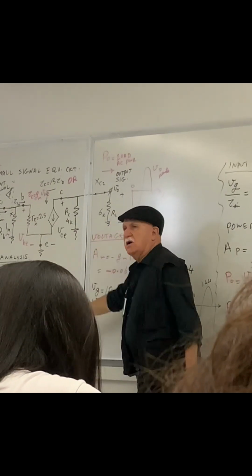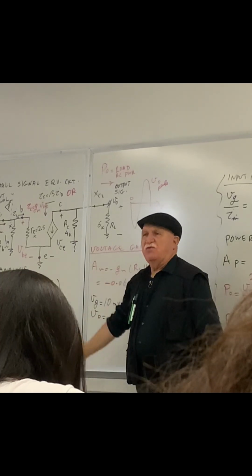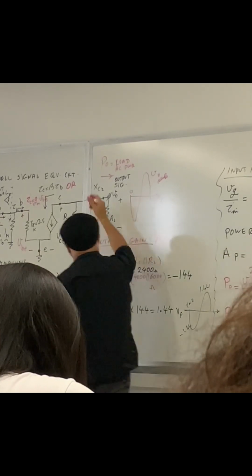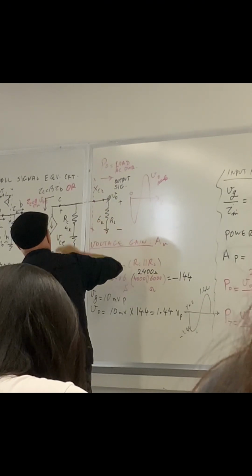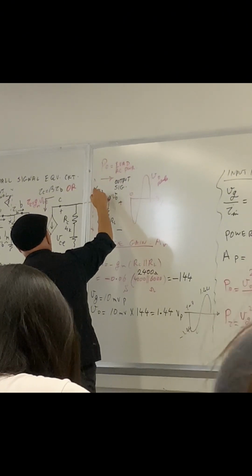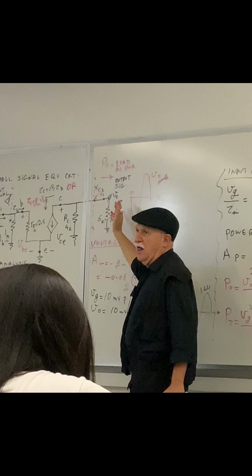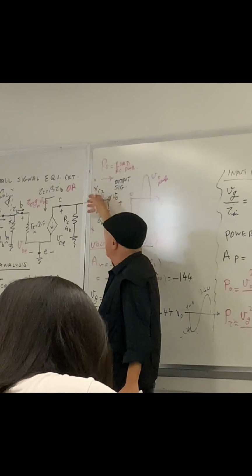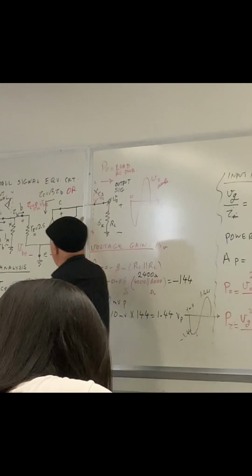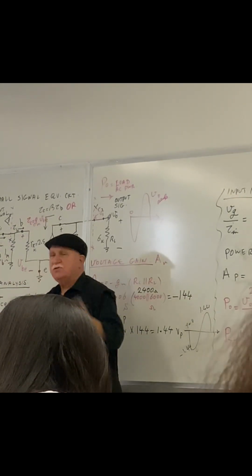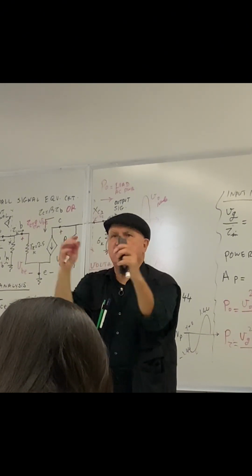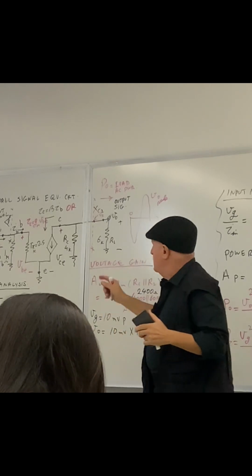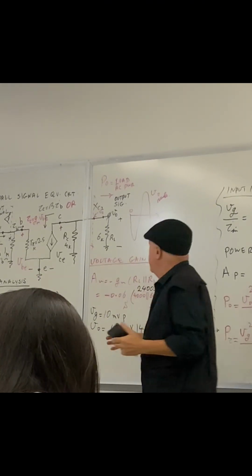Load resistance RL, often we want to model our amplifier in the absence of RL. How do we proceed with that? In other words, we want to cut from here, still define this node as VO, but without RL. And we want to look back and present all of that circuit with a neat voltage-dependent source with one block. It is more simplified than what you have over here.